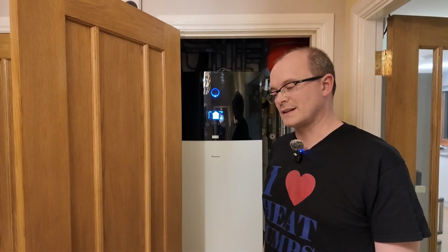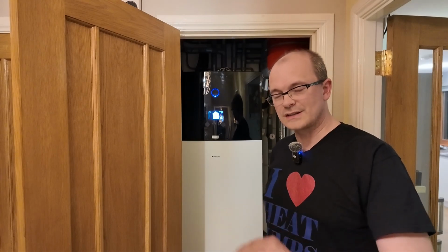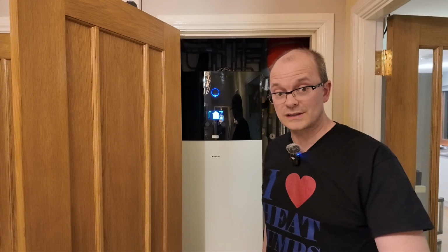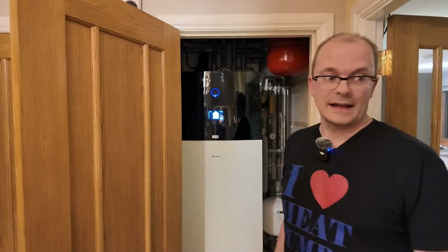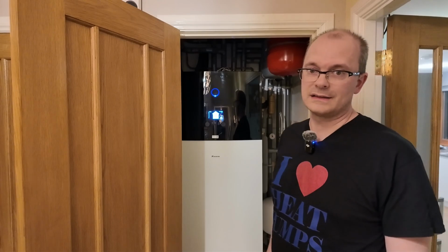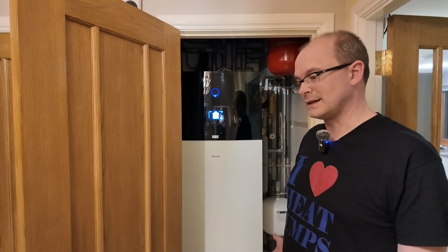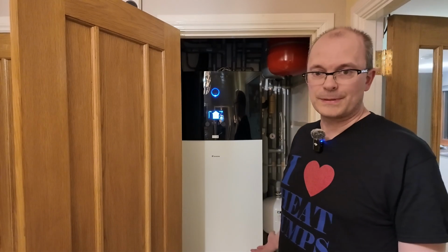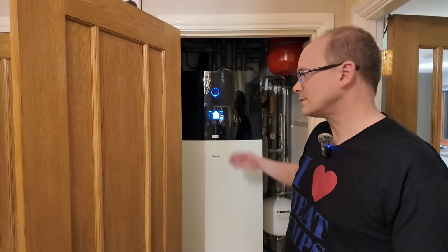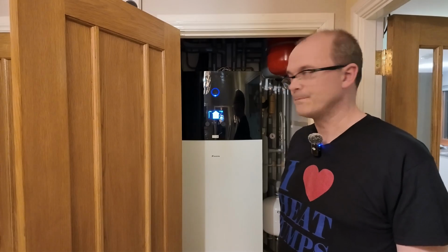What I find is that it will stay at 28 degrees Celsius set point water temperature for temperatures above 10 degrees Celsius, which is fine, and the room thermostat will cut out as and when needed. Above 10 degrees, lots of solar gain in the springtime. In the autumn time, there can be plenty of cloudy days when the temperature is 10 degrees, and then the heat pump will do its thing just fine.